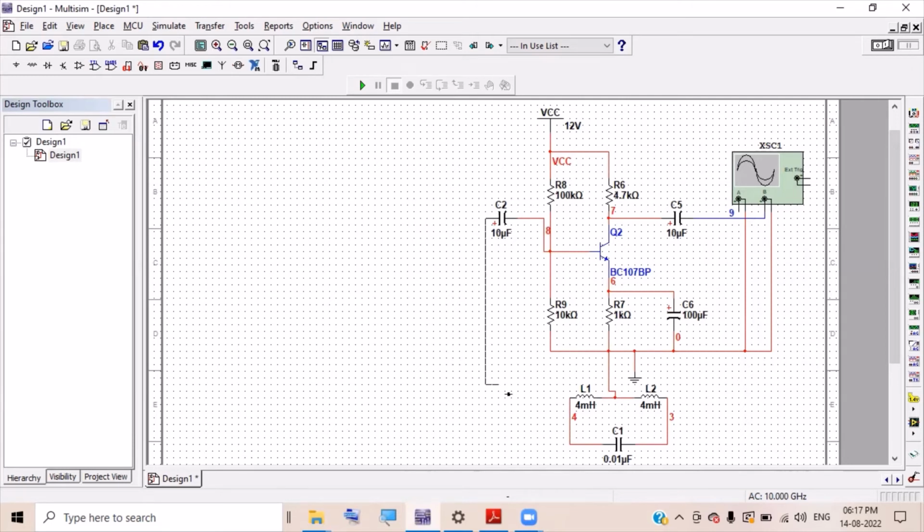And what we need to do here is connect this point here, and then we have to connect the output. So this point we have to connect here. For that you can go for Control J. We don't have a node here, so Control J. Place the node here, and now we can connect this point here. Okay.